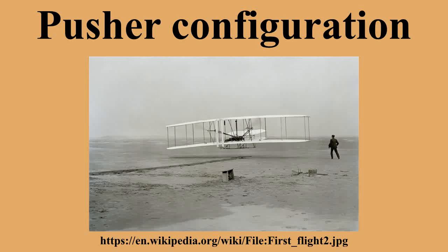On tailless pushers such as the Rutan Long-EZ, the propeller arc is very close to the ground while flying nose high during takeoff or landing. Objects on the ground kicked up by the wheels can pass through the propeller disc, causing damage or accelerated wear to the blades, or, in extreme cases, the blades may strike the ground.